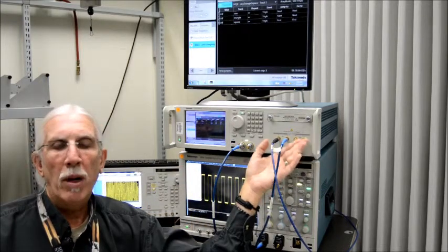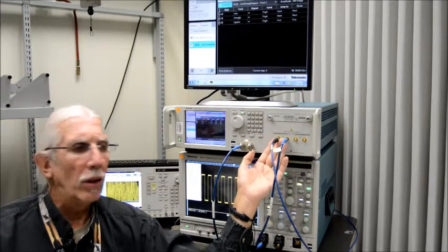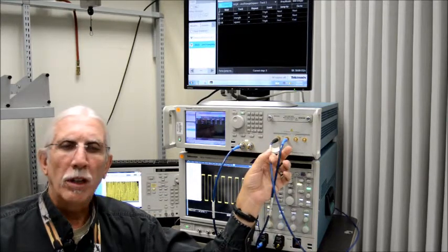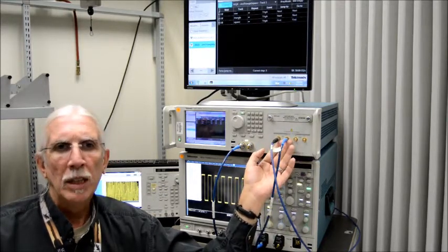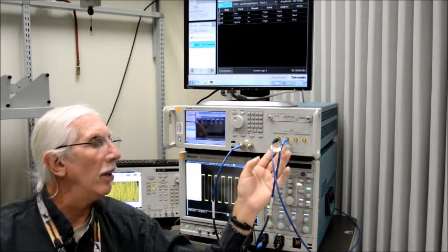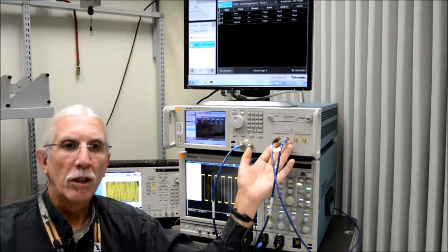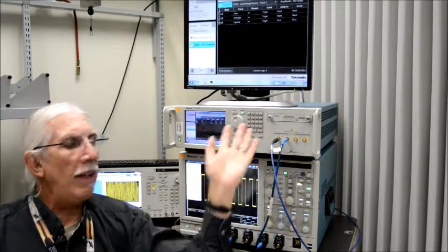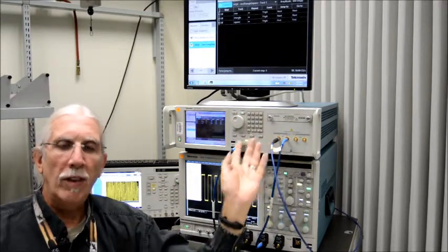And then we also have marker outputs here for use as a trigger or for using as a pattern generator. It's basically a digital output. We have 2 markers per channel. It has an easy interface so that you can do everything from the front panel.